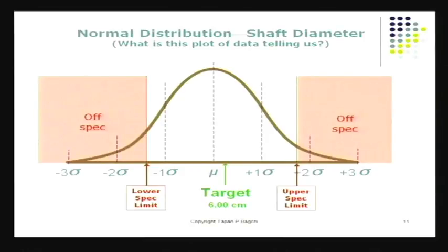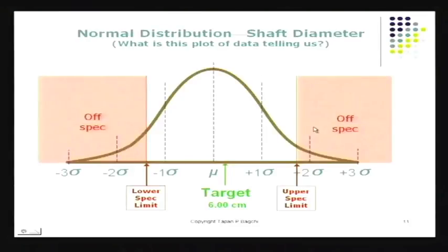That is also something that we'd like to be able to do. If I do not control these things, and if I just look at the output of a process which is not being controlled either for accuracy or for precision, we'll end up with performance that looks like this. Now, before I show exactly what is going on here, the quality characteristic is plotted on the x-axis. Now, there is a limit here which is called the upper spec limit for the parts. And this is the upper spec limit, which says if I produce parts which have dimensions beyond this upper spec limit, those parts are going to be useless for application.